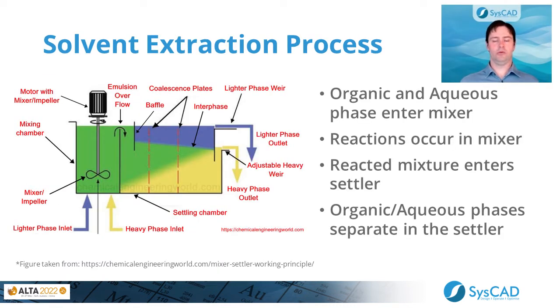So now let's talk about what we're going to actually do today. We're going to look at the solvent extraction process. For those that aren't familiar with solvent extraction, I'm going to go over quickly what a solvent extraction cell is. This is a solvent extraction cell. On the far left-hand side with the mixer, you have the mixing chamber. In this, you have the mixing of organic and aqueous. They are mixed intimately over a period of approximately 3 minutes or so, and they hopefully come to equilibrium.